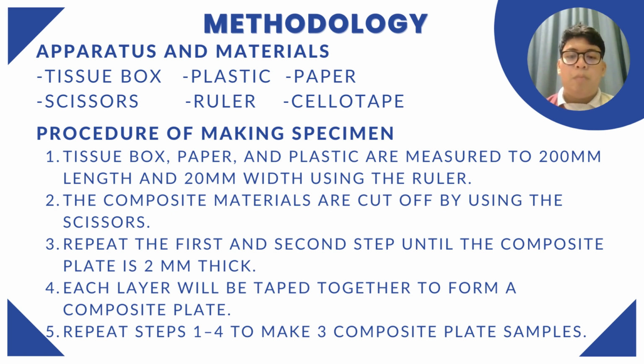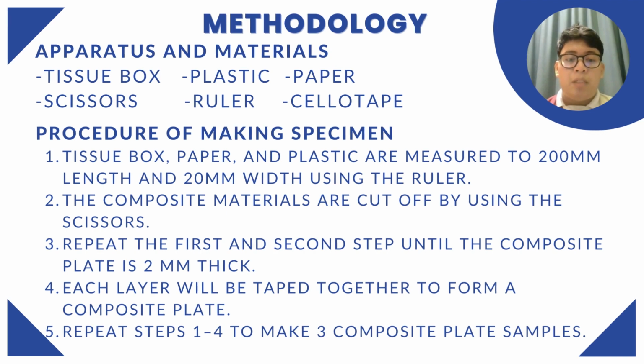Third, repeat the first and second steps until the composite plate is 2 mm thick. Fourth, each layer is taped together to form a composite plate. And lastly, repeat steps 1 to 4 to make 3 composite plate samples.